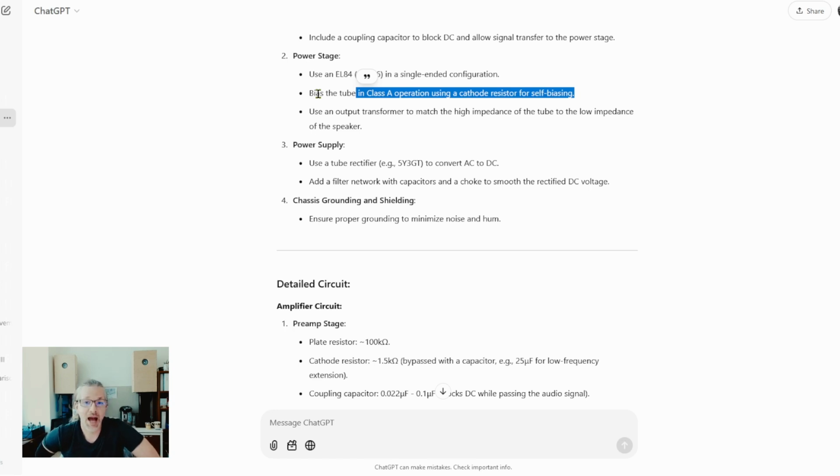You can even have higher power than the fixed bias if you increase the plate voltage of the tube in comparison to that circuit that you originally started with. Anyway, that was just a segue about self-bias versus fixed bias.